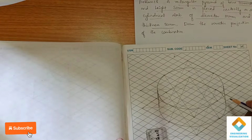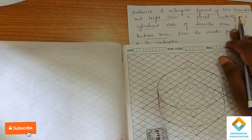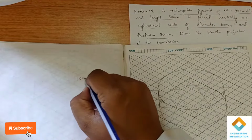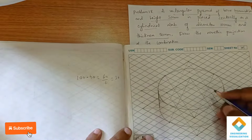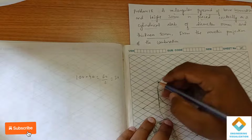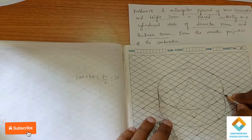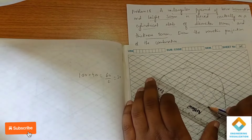So above it you have to construct a rectangle or a pyramid of dimension 40 into 25. So 40 into 25. You can place 40 here or here. So 100 minus 40 means it is 60, divided by two sides means 30. So on this top side I'm going to mark 30 here, and from this side also 30. Okay, so 30 is marked. Second, draw a line here.